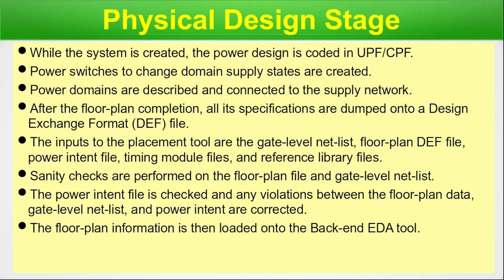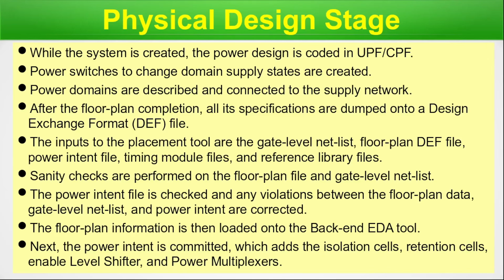The floor plan information is then loaded onto the backend tool. Next, the power intent is applied, which adds isolation cells, retention cells, enable level shifters and power multiplexers. And the backend versions, that is the layout versions of these cells, are picked up from the standard cell library. So that was all about the implementation of the retention cell in the physical design stage. So done here. Let's move on to the next slide.